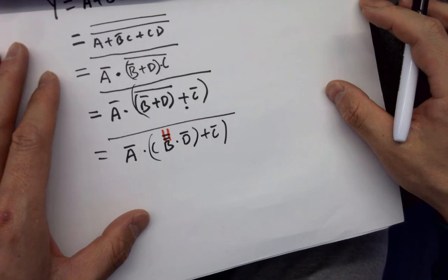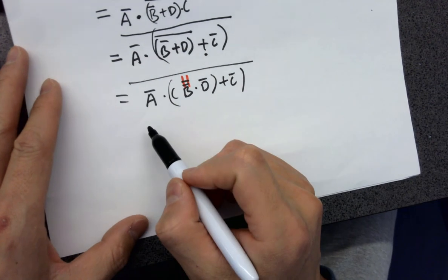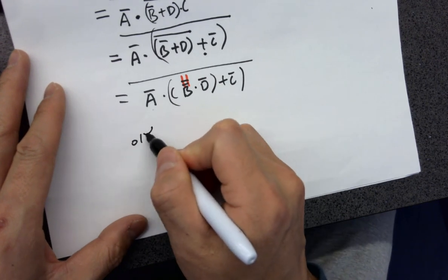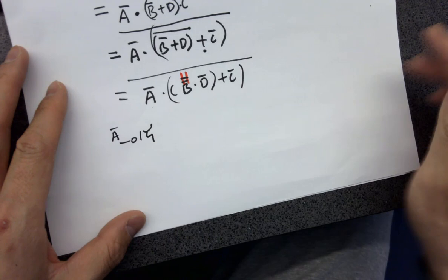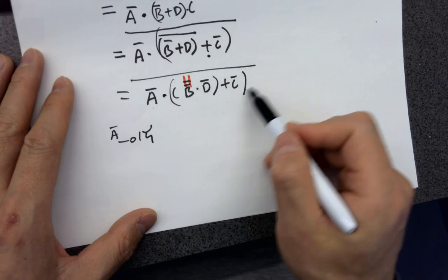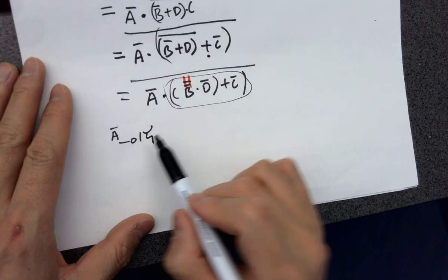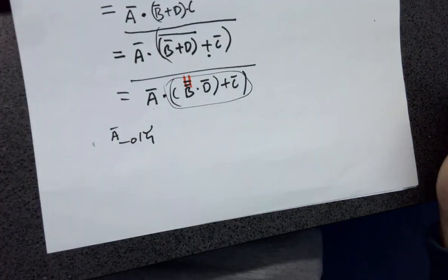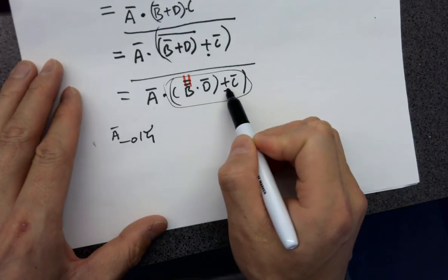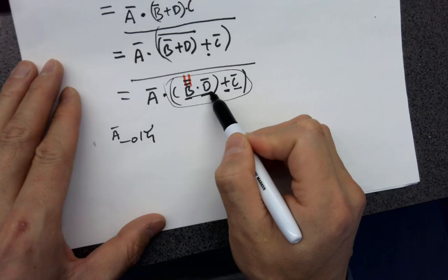Now we convert it to the schematic. Okay? See what that looks like. Where should we start? A, right? A naught. It's a NAND gate, right? It's a NAND gate for this logic. This is a whole block here. So these should be in parallel with this whole thing. It's A naught PMOS. And you have D, because this is a NOR gate, so this and this should be in series, and this should be in parallel.